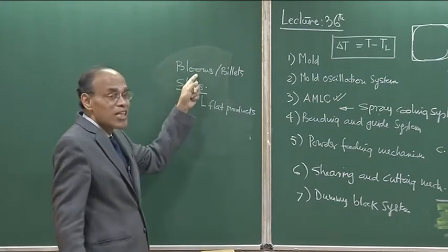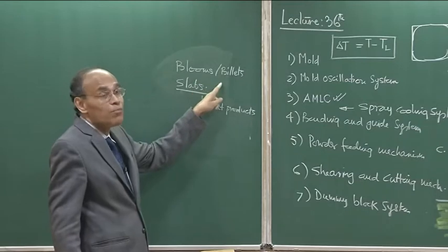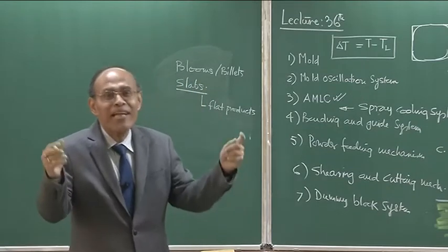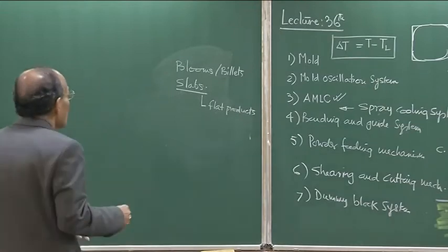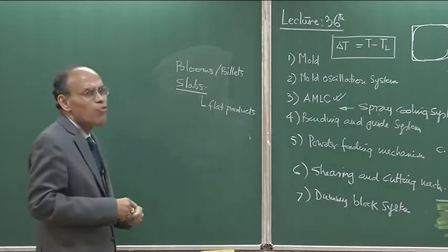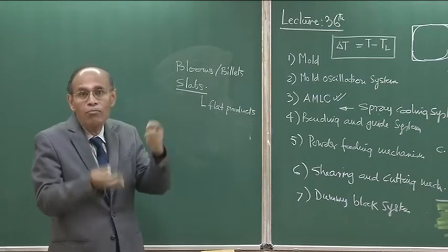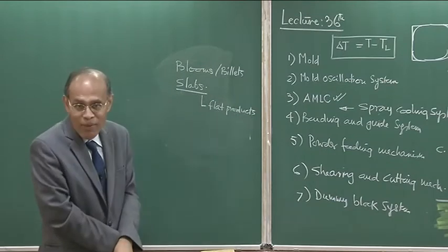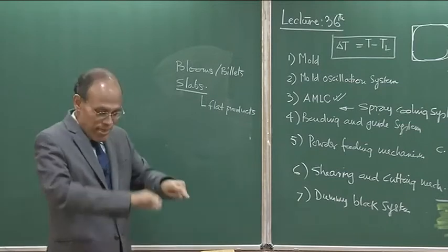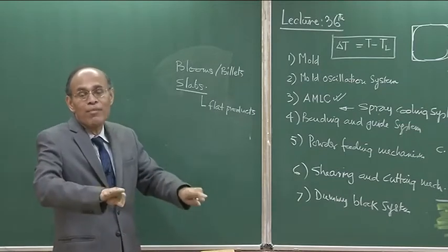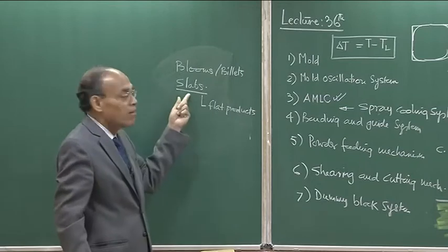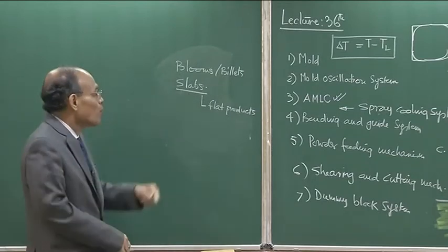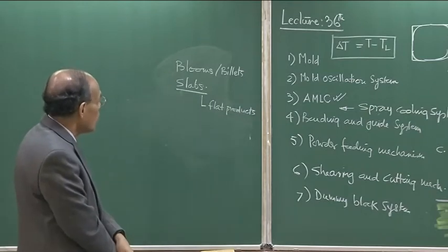On the other hand, special steel plants mostly produce blooms and billets, and these blooms are used for making crankshafts, automotive parts, and so on. There are of course mills which produce both kinds of products, simultaneously a long product plant as well as a flat product plant. On a daily basis, maybe two thirds of the heats are routed to produce slabs, and one third to produce the long products, billets or blooms.